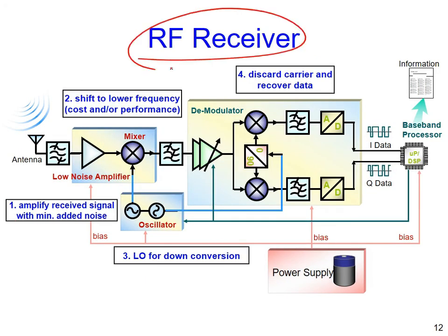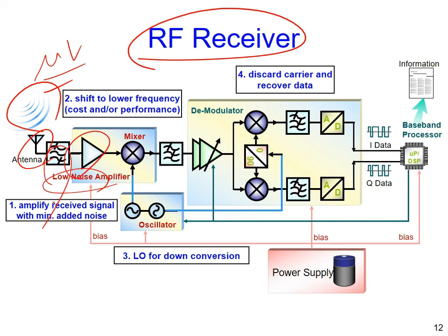Then at the receiver side, the same RF signal will be received from your antenna. How much is the magnitude? Only microvolts. In this part, there is some filtering and image rejection. I wouldn't like to teach you too much of that. Then we need the help of the local oscillator and LNA to convert the radio signal to midband and then to baseband. Reverse it.